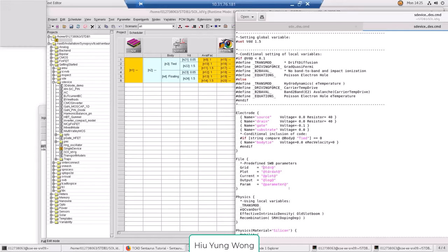So this tool is smart, SWB. When you see @tdr@, it knows that it's going to take the file from the tool that is on its left, the nearest tool that is on its left. So you check, okay, for N9, the nearest tool is N1. So it's the output of N1. And because this is SDE, by default, the output is N1_msh.tdr.